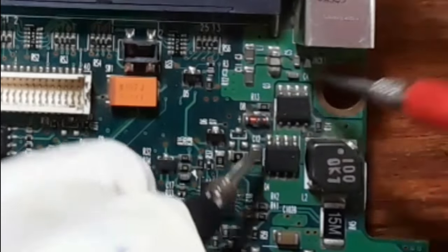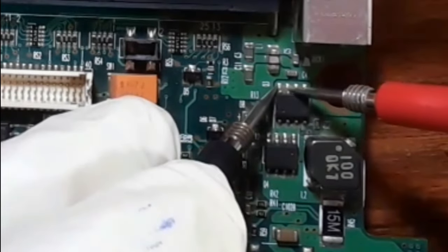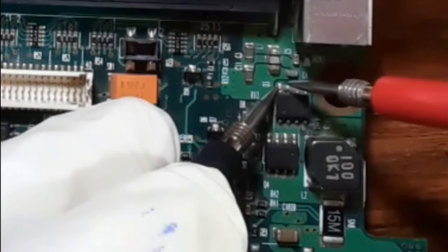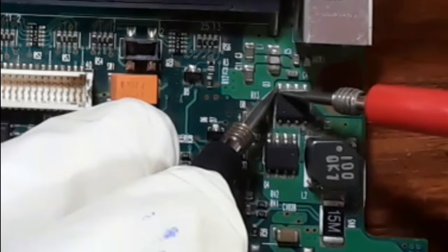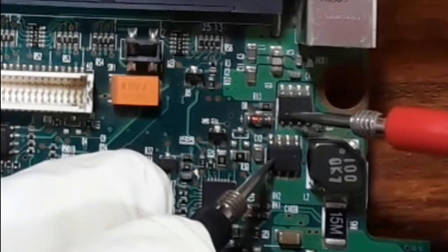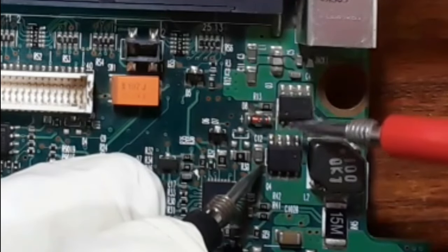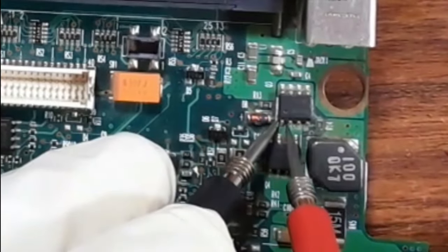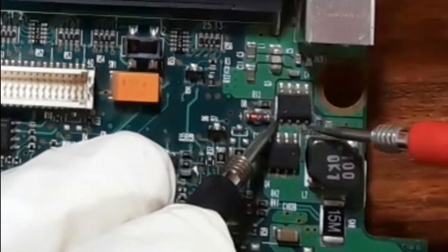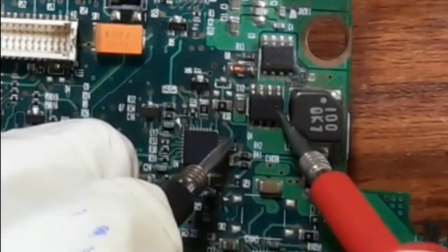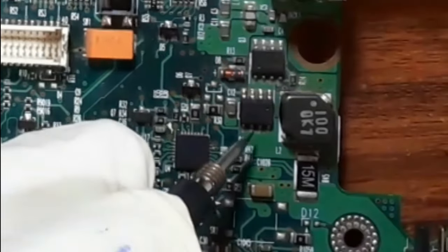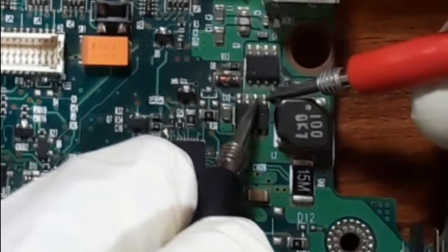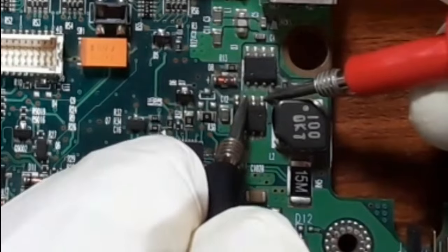Here we have the drain. Let's check it. As you see, this is the drain, with 4 pins connected together. Here I have the point, which means this is pin number 1, the source. These 3 connectors are source, and here we have the gate. So this point means pin number 1, so this is source. These 3 pins are source.